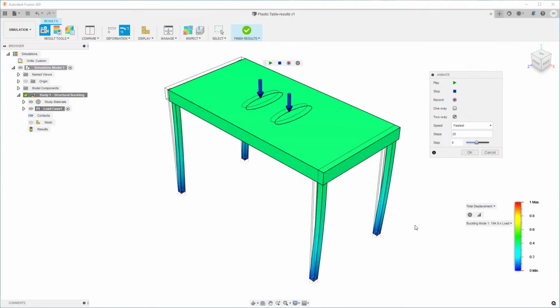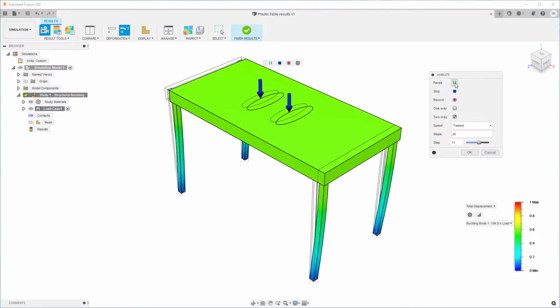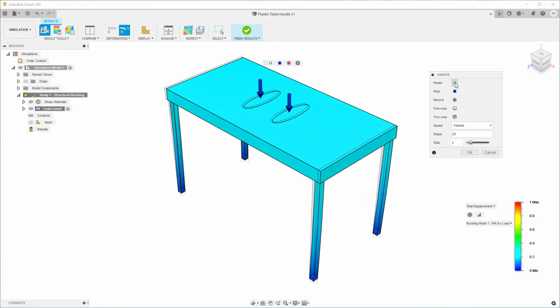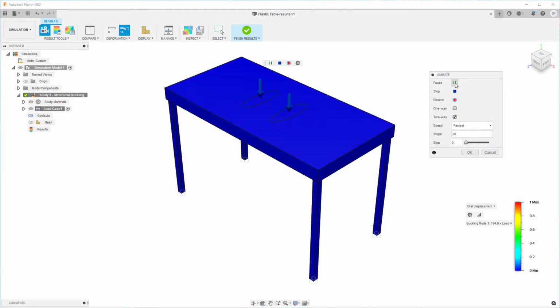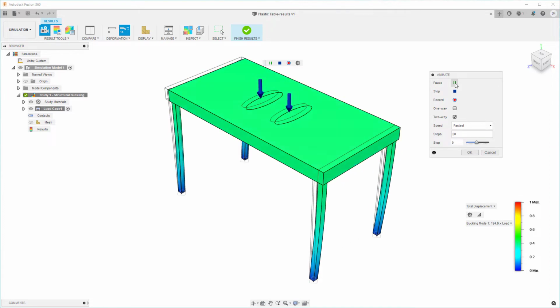In this video, we will discuss structural buckling. You may be wondering what buckling is and why simulate it during the design phase. The technical explanation is when an object is very long in comparison to its cross-sectional area and becomes unstable under a compressive load. You've probably seen this in plastic furniture or standing on something that wasn't intended to hold the weight of a person. The instability can end in a catastrophic failure, which personally I'd rather see on a computer.